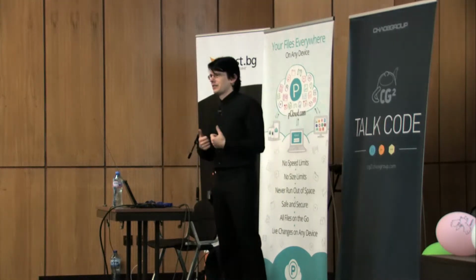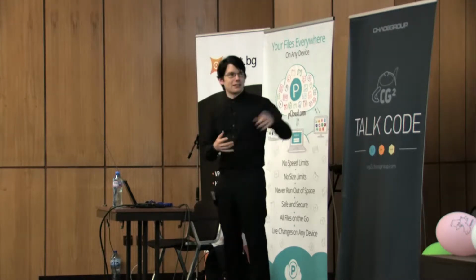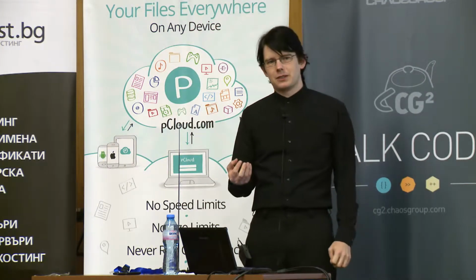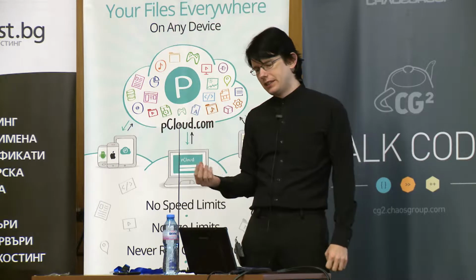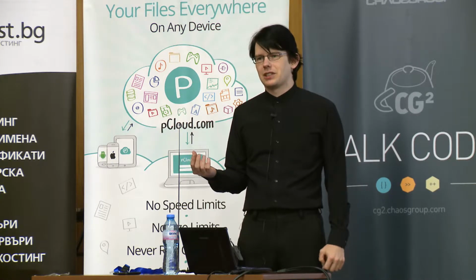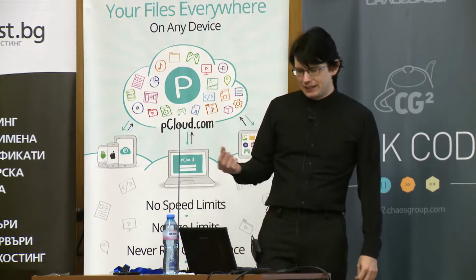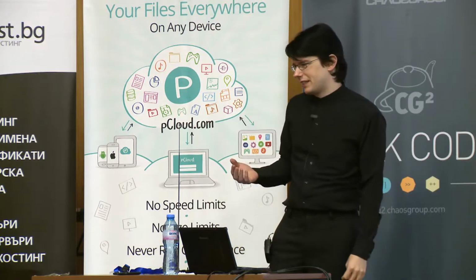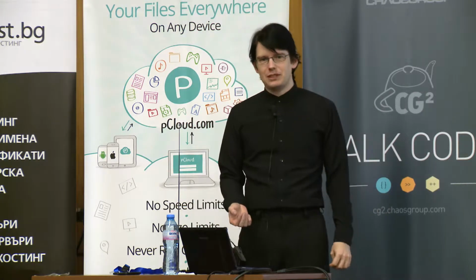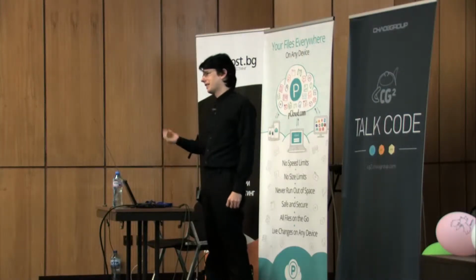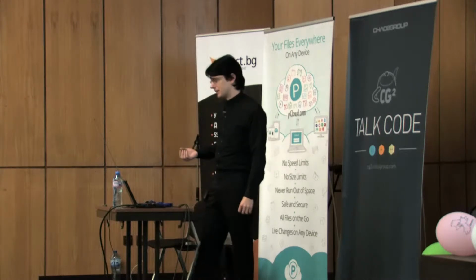So what some of the vendors who built these USB sticks did is they activated that mode, and then you get the raw samples of the baseband into the PC, and in the Windows software, they implemented a DAB receiver for digital audio broadcasting. And then some people figured that out, and they started to do protocol tracing on the USB to find out how on earth this chip can get set in this special mode so it sends the raw samples over into the PC.